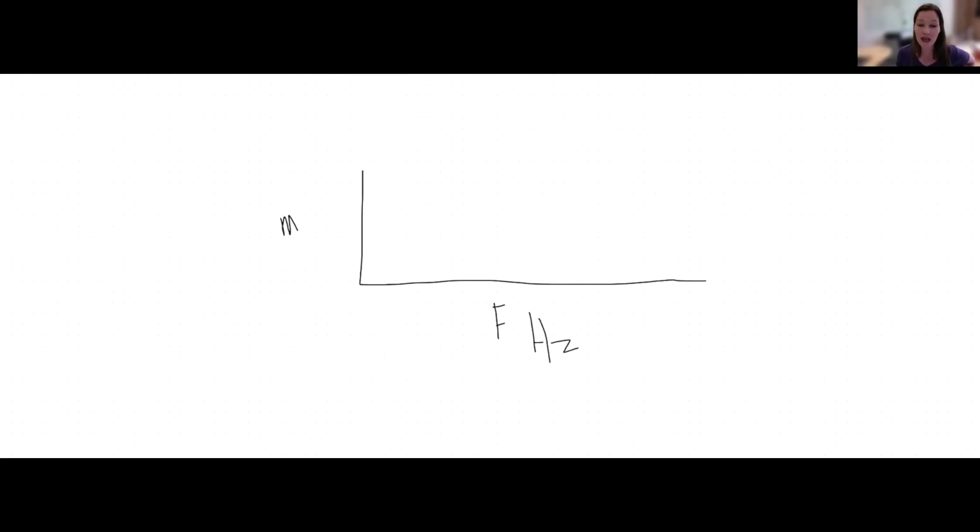And then we'll compare that to a band pass filter where we have a band. So the filter design is going to look something like this, where we're filtering out low frequencies, we're keeping some specified frequency range, and we're filtering out high frequencies. And we're also going to look at the frequency composition of the original data compared to our filter design.